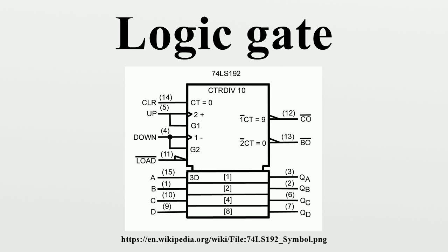When using any of these gate setups, the overall system has memory. It is then called a sequential logic system, since its output can be influenced by its previous state, i.e., by the sequence of input states. In contrast, the output from combinatorial logic is purely a combination of its present inputs, unaffected by the previous input and output states. These logic circuits are known as computer memory. They vary in performance, based on factors of speed, complexity, and reliability of storage, and many different types of designs are used based on the application.